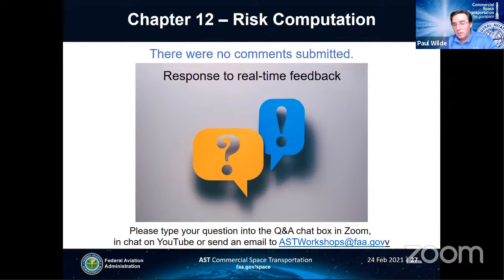I think some of the questions about the winds were aiming at that, but clearly there will be wind constraints that you wouldn't want to fly your vehicle through, and also there could be wind constraints where, given the size of your hazard area around the launch point, that hazard area would not be valid if the winds exceeded the launch commit criteria. Thanks.